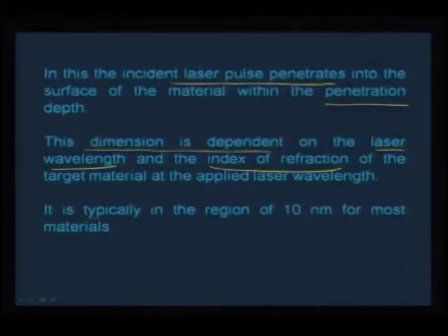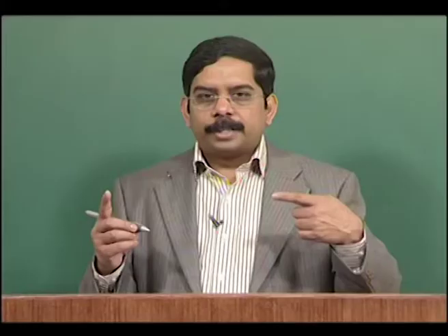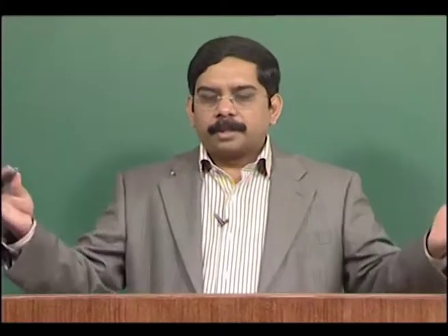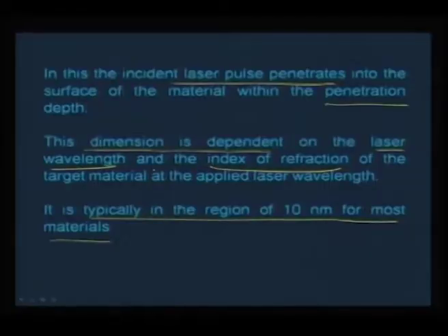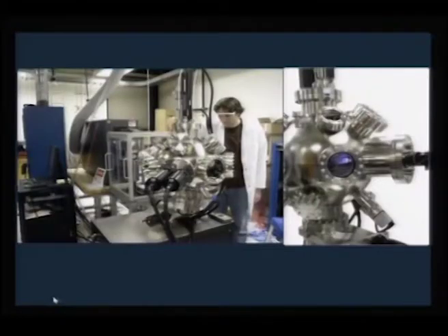So it is typically in the region of 10 nanometers for most materials, meaning the penetration depth. If you can achieve this much, then you can actually bring the surface of the material out in the form of a plume. Typically this is how laser PLD will look.